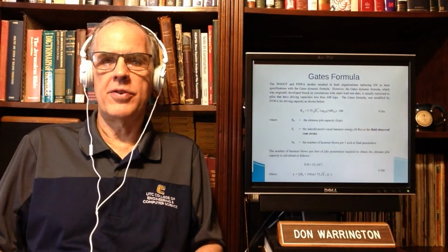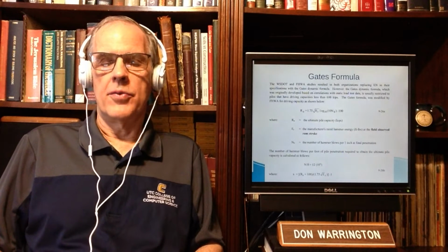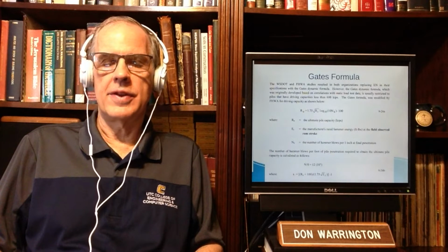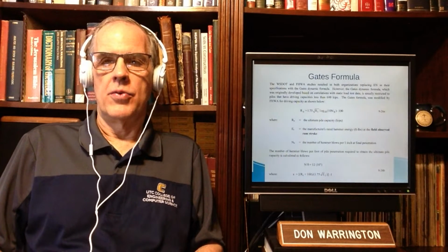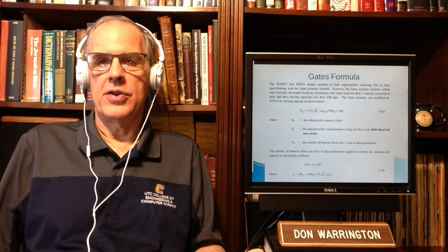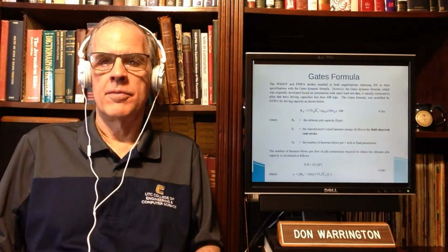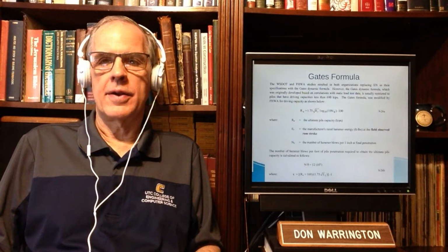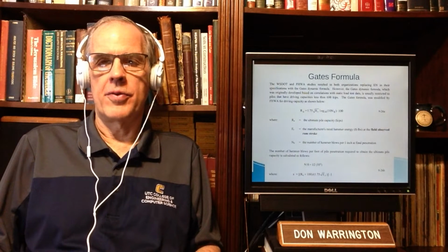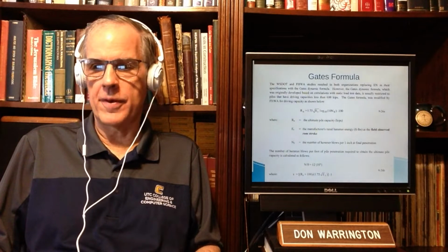The one place where you see the engineering news formula used on a regular basis, and we're going to explore why that is with ENR and other dynamic formulae, is wood piling. Wood piles are more suited for dynamic formulae than other types of piles, for reasons we're going to discuss in a minute. But this one is the Gates formula.